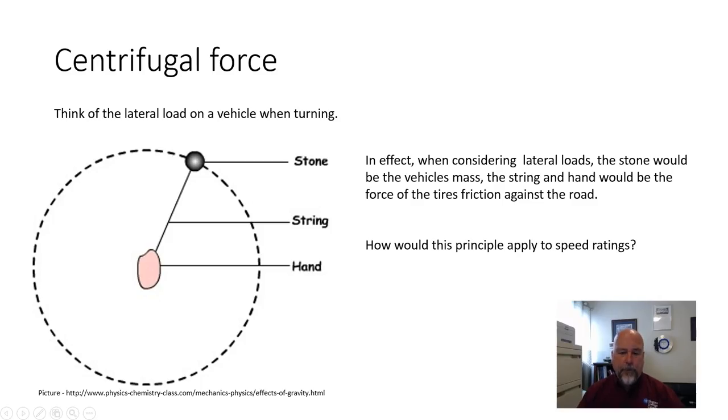Centrifugal force. Now, centrifugal force is just one of those laws of physics. Things work the way they work. But there's something to consider here. The faster you spin a tire, the more force is applied to the tread. So if we look at this, we can consider the stone in this drawing to be the tire tread. We can consider the string to be the cords in the sidewall of the tire, and the hand here, basically, that'll be our axle that we're rotating around.